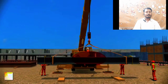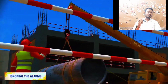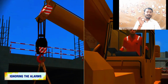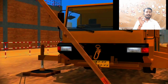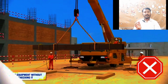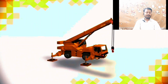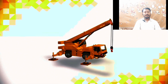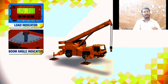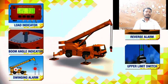For example, not using the load chart, ignoring the alarms, etc. Using equipment without checking it and its safety. Not following the guidelines of maintaining the equipment according to the manufacturer's instructions. For example, not checking load indicator, boom angle indicator, swinging alarm, reverse alarm, upper limit switch, etc.